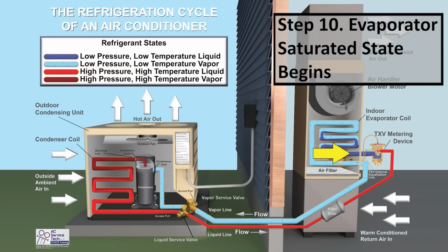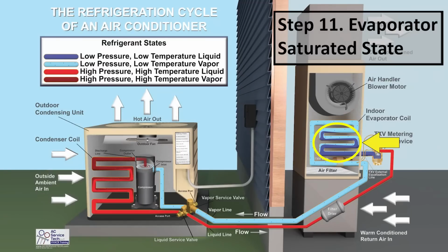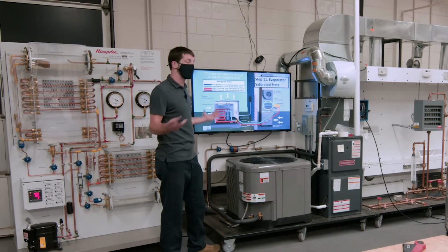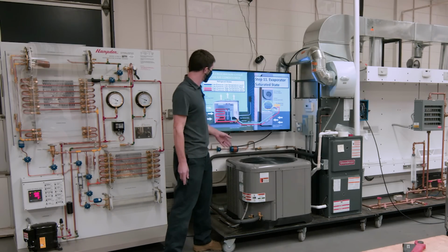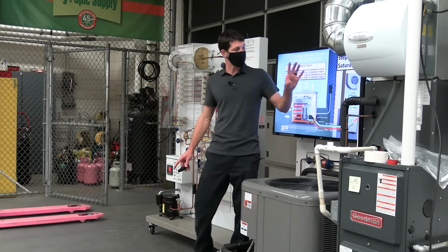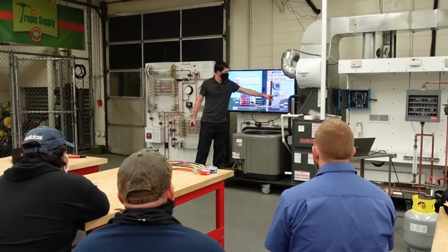It's kind of, it's saturated. Saturated may not be a state, but it's saturated. So right here, this whole thing is saturated, and we talked about this before. Just say it's 40 degrees. It could be 36 degrees. It could be 44 degrees. That has to do with the liquid pressure of the subcooled liquid refrigerant and the indoor heat load. That will change your pressure.